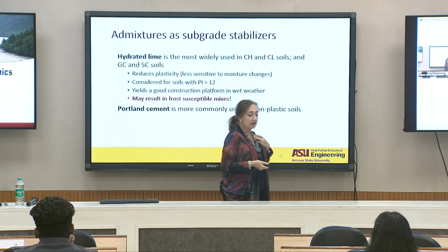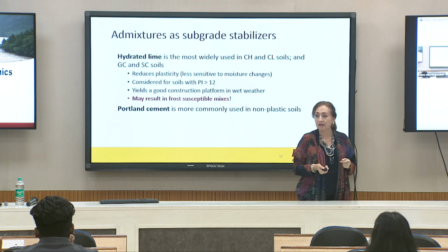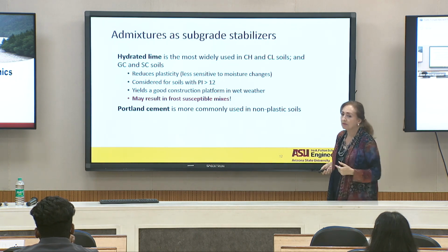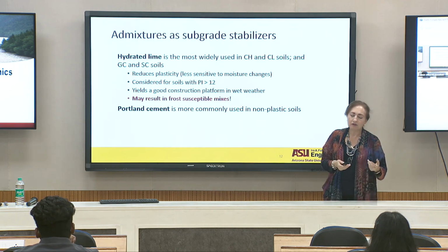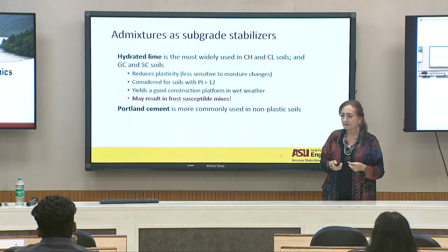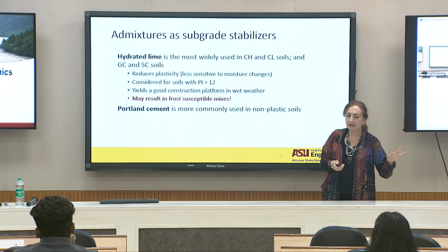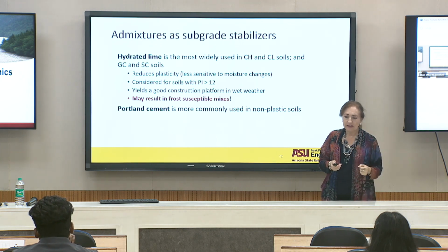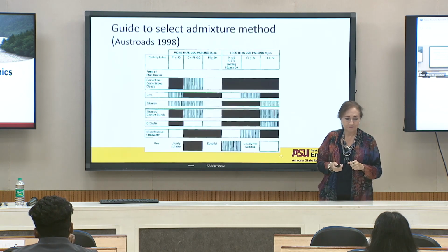Portland cement is more commonly used in non-plastic soils, all right? So you have gravels, or soil that I need to stabilize on the granular side, or with less clay material, then we use cement for that.